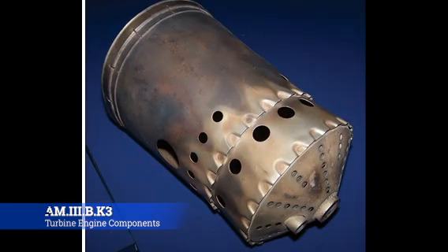Okay, here's the combustion section. Now we've gone from the air inlet, we've compressed the air, and now we're actually going to light fire to it. The primary function of the combustion section is, of course, to burn the air-fuel mixture, which adds heat energy to the air and helps the air start to expand and spin the next stage. To do this efficiently, the combustion chamber has to do four things. One is to provide the means of proper mixing of fuel and air for good combustion. We're going to talk about the igniters and the injectors in just a second.